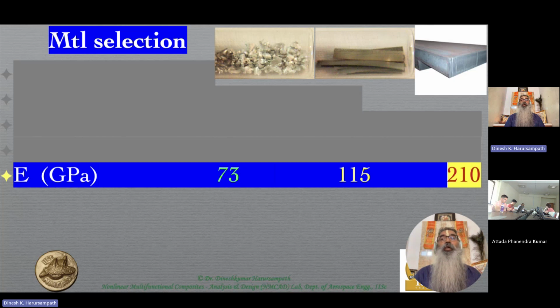Which means you're dividing that quantity, whatever we saw in the previous row, that is the sigma U's, or a much smaller value, which is the sigma at the proportionality limit, by that particular strain limit in order to reach this slope, because you start with 0, 0. So that's the slope of the sigma versus epsilon curve, in particular a normal stress versus a normal strain along the same direction. That's why the E values are typically much, much larger compared to the sigma U values.